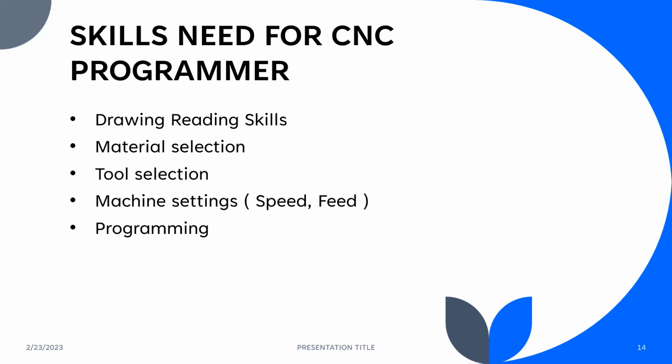Next one is machine setting. In machine setting, we have workpiece setting, and also the machine zero point is there, and here only we can fix the speed and feed. Feed means the depth of cut. So how much speed we need, how much feed we need. Next one is programming knowledge. So these are the skills needed for CNC machine operators.